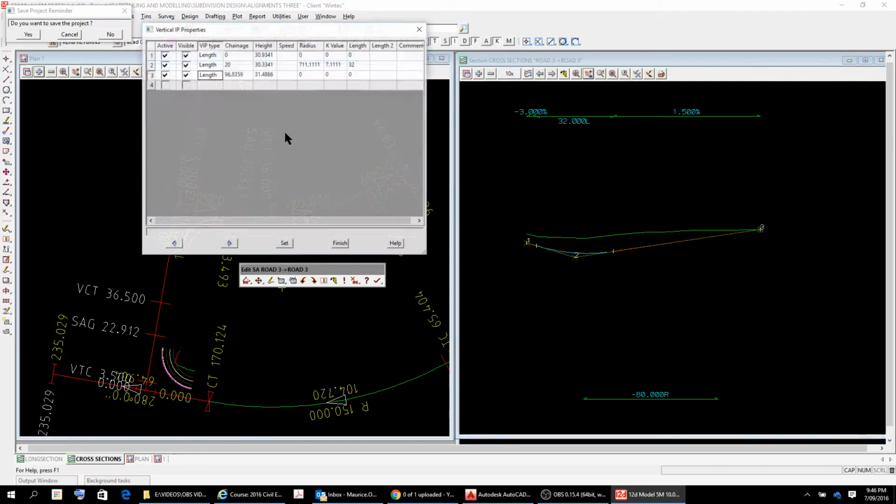There's the VIP, and yeah, I've changed that to 32, just so that that gives us a little bit, 4 meters there before it changes with the curve, and then gets it up into there and raises this low point in here, which if you click on there, whereas previously we had 30, we now got 30.6, 30.5 it would appear.